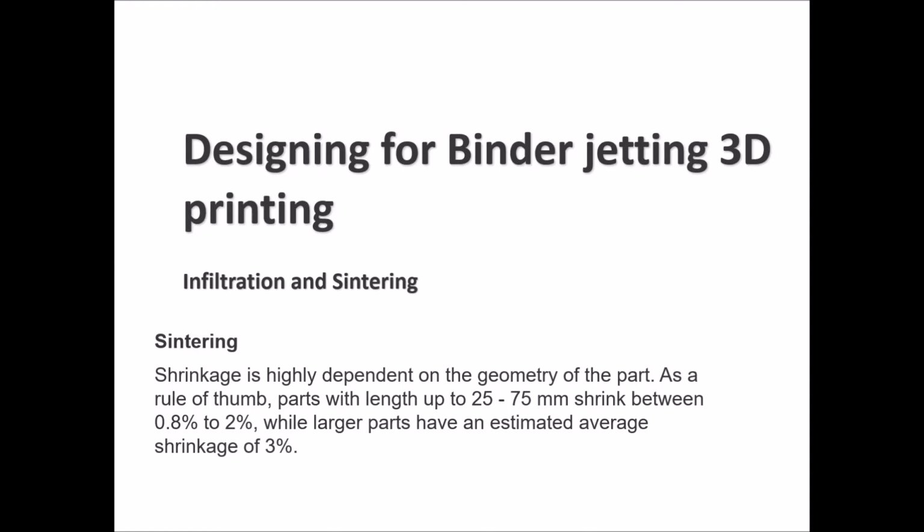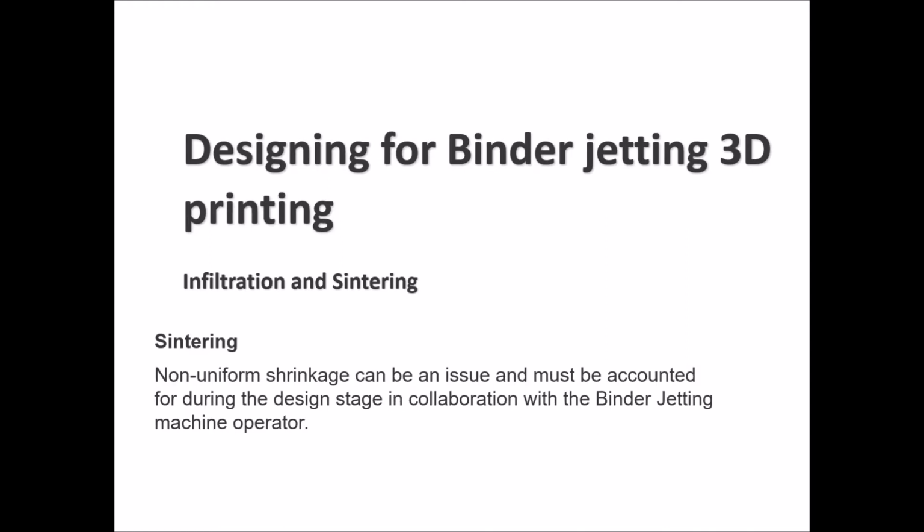For larger parts, it will have an average shrinkage of 3%. Again, these are averaged values. It could differ based on the quality of the material you're using. It depends on the accuracy of the printer that you're using. Of course, binder jetting printers are made by many manufacturers, so results are not all the same and accuracy is not the same.